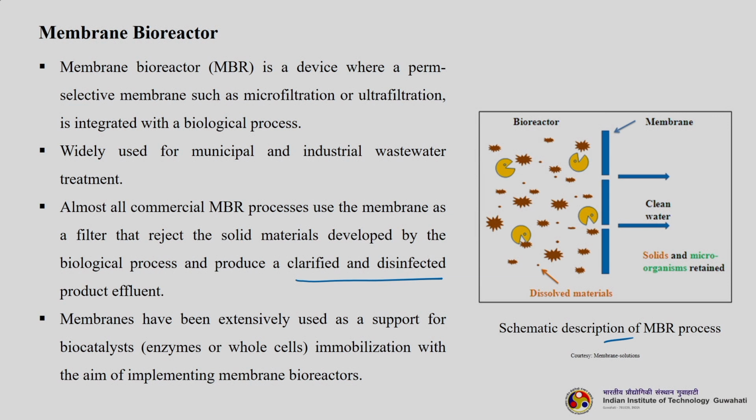You can see the bioreactor here, the cells are there, maybe extracellular enzymes, other biocatalysts also. The membrane is helping to retain everything on the side where the biological reaction is happening, and whatever is unwanted will pass through the membrane. So, solids and microorganisms are retained, and clean water comes to the permeate side.